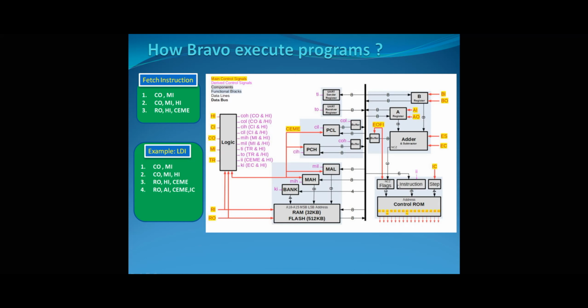And then, of course, we have our instruction register here that is reading the instruction. When the instruction is put from the memory address onto the bus, it can be read into our instruction register. And finally, we have that little micro step counter here. As you can see, the outputs of all these three sections are combined together, and that will be addressing our control ROMs, and our control ROM will be outputting our control signals.